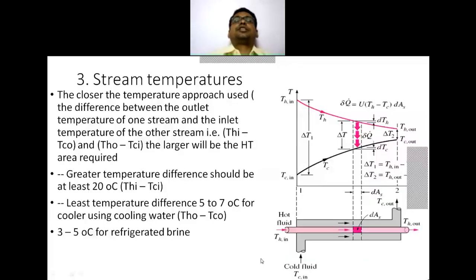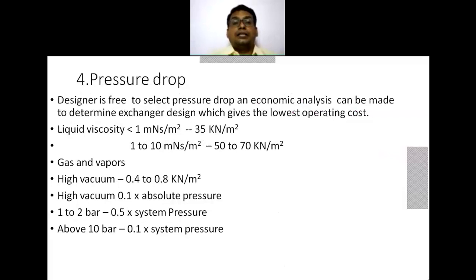The next is the pressure drop. The designer is free to select the pressure drop, but by considering this pressure drop, my operating cost increases, and as a result there is a need to study the economic analysis. So based on the economic analysis, one has to optimize the operating pressure drop. What should be the operating pressure drop?